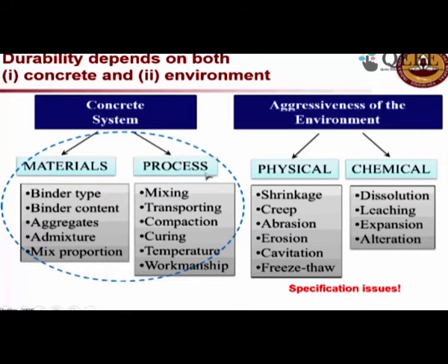And if you are talking about the process of concrete making: how we mix the concrete, how we transport, compact, curing, temperature, workmanship. All these are very crucial when we talk about deciding the durability of concrete.